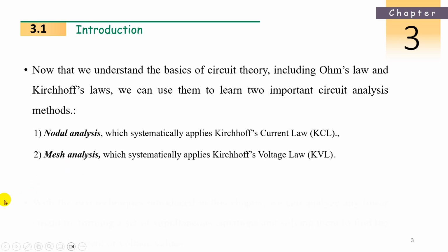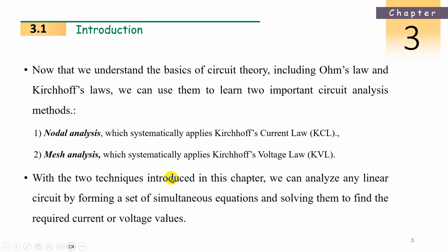When a loop is there, Kirchhoff's voltage law applies. With the two techniques introduced in this chapter, we can analyze any linear circuit by forming a set of simultaneous equations and solving them to find the required current and voltage values. How to solve? We have 2 or 3 methods, and I will discuss only 2: the elimination technique and Cramer's determinant method, the matrix method.